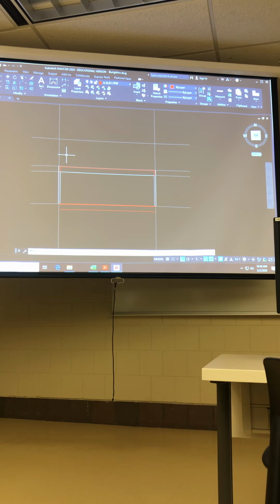And I'm going to draw the outside of my truss from the outside face of framing up to that corner, that work point, where my top chord is. And I'm going to offset that line 5.5 inches as well, because all of the web members, again, are 2x6s.